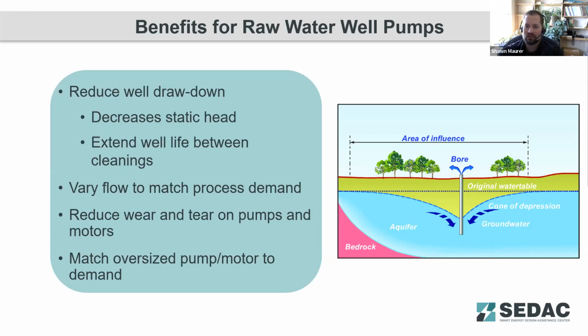You can also extend the well life between cleanings by doing something like this, because you're not drawing water as fast through the aquifer, so you're not clogging up the filters and bed material around that with smaller grains and things that can clog that system up. So you extend the operating life of your well between major cleanings and things like that.